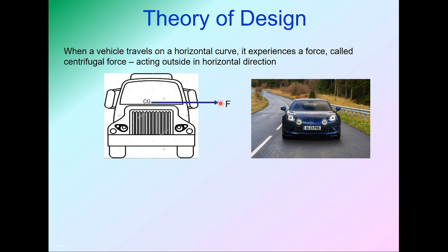So let us say F is the centrifugal force, which is horizontal, and W is the weight of the vehicle, which acts vertically. Now the resultant of these two forces, horizontal and vertical, is R. And if B is the wheelbase of the vehicle, then this vehicle will be in a stable position as long as this line of resultant force does not pass outside of the base. Meaning this red line will pass through a point on the wheelbase which is between the wheels of the vehicle.